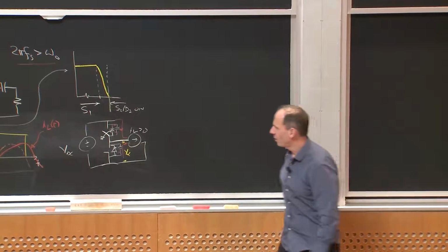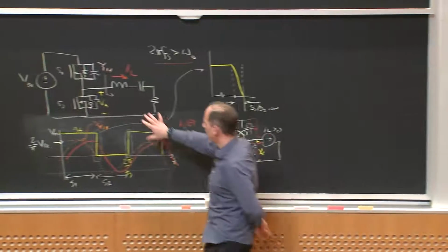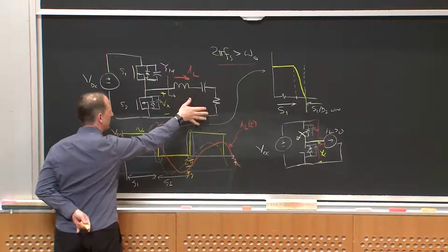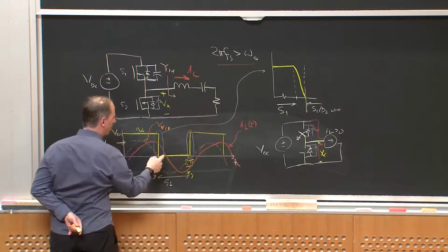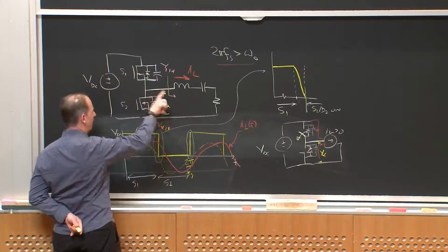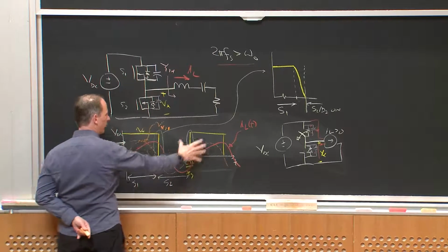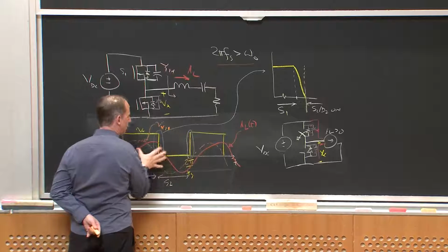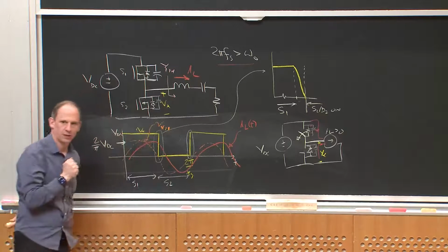So it's sort of a long way of saying, because I have this approximately sinusoidal current, and I've made it inductive, I phase delayed it with respect to where the voltage is, I get naturally the opportunity to do 0 voltage switching.